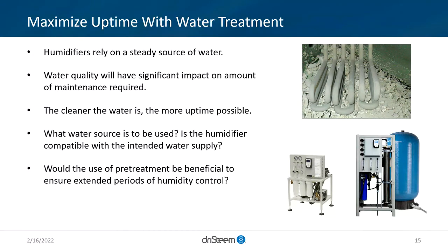So looking at water quality is important, not only from that, but within these humidifiers there's scale management, essentially, or cycles of concentration. If we can eliminate how much total dissolved solids are in there, that will decrease our draining frequency. If we decrease our draining frequency, that means less refill, less potential for quenching that boil. So really, thinking about it, cleaner water equals more uptime.